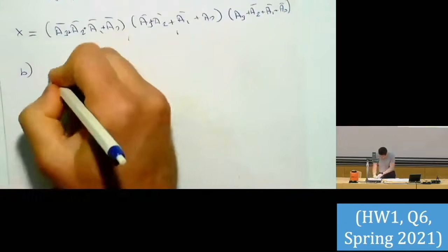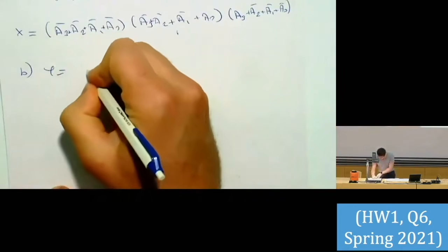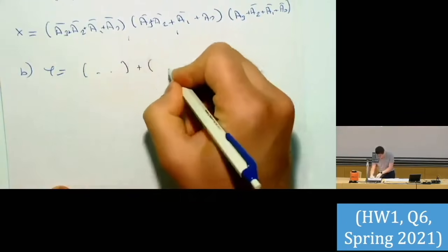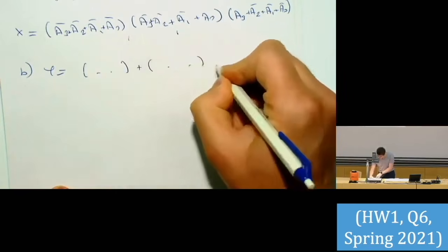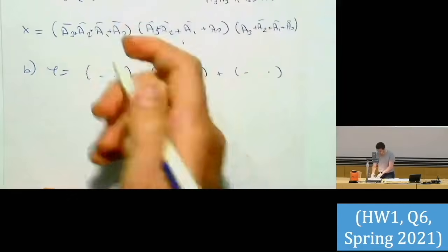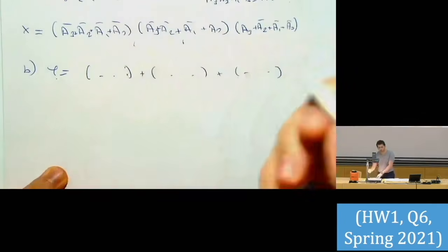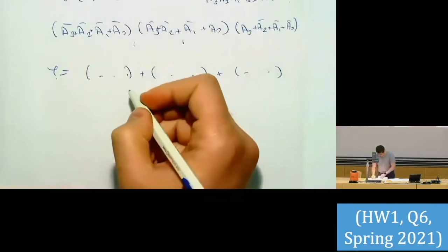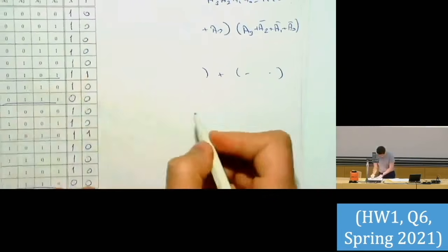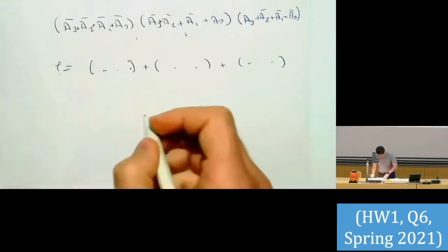So what sum of products is, is that I have terms, those terms are ANDed inside, and outside those are ORed. So Y is 1 if one of these is 1. Let's write it that way. To make Y 1, I have two options, either that or that.